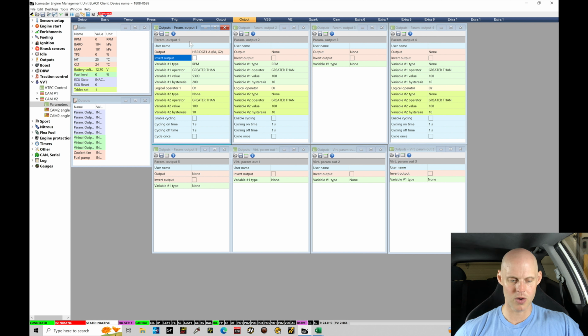There's actually a better way to enable VTEC that gives us more programming flexibility. Since we know H-bridge 1 is where they've wired it, I'm going to get it off of this area right here. We'll go to none, and we'll set it up in a different area when we get into the cam. There's an actual VTEC programming window. It gives us more programming flexibility rather than just basing on RPM. We can use RPM, manifold pressure, and throttle position, which gives us a better control range.